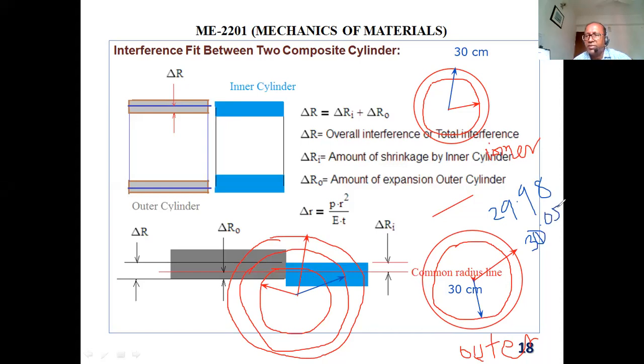Nothing can be made with accurate dimensions. That means there is some tolerance. So in one place it will slide, in another place it might hold tightly. If it slides after pressurizing, then when you burn all your gases, or the inside pressure is reduced, it will slide again. So the life of the cylinder will be reduced. So for that reason,